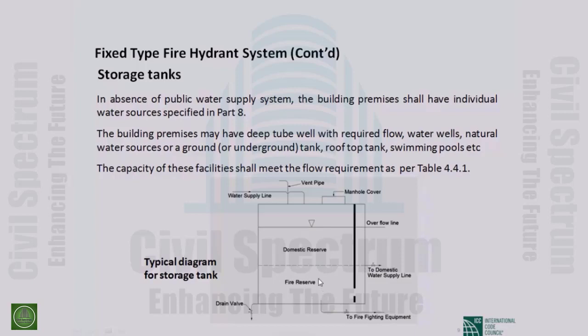In no case will it be drained out by domestic requirement. So there will always be a certain amount of water for firefighting. But there is a problem with this design. The lower portion of the water will not recirculate. In Bangladesh there will always be mossing, that means fungi and algae will grow very fast, and there will be some sedimentation deposition.